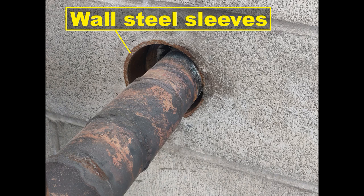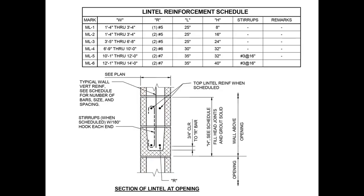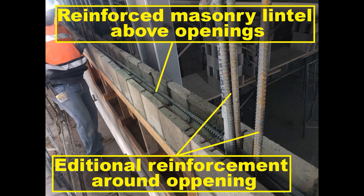Carefully make openings in the masonry so that wall plates, cover plates or escutcheons required by the installation will completely conceal the openings and will have bottoms parallel with the masonry bed joints. Provide reinforced masonry lintels above openings over 12 inches wide for pipes, ducts, cable trays, and other wall penetrations, unless steel sleeves are used. Do not reduce masonry units in size by more than 1/3 in height and 1/2 in length. Do not locate cut products at ends of walls, corners, and other openings.